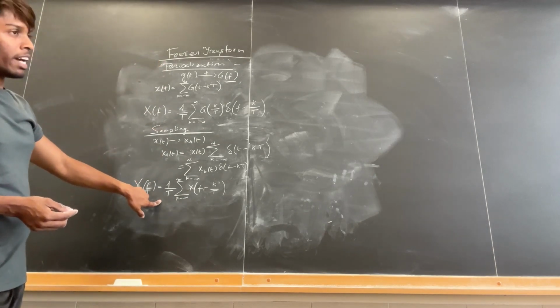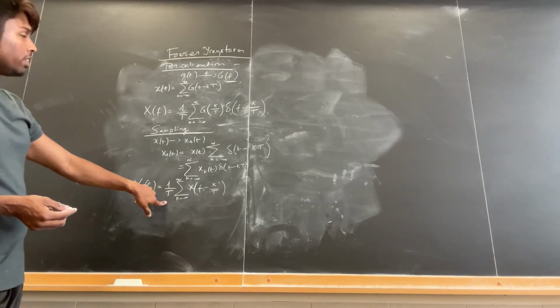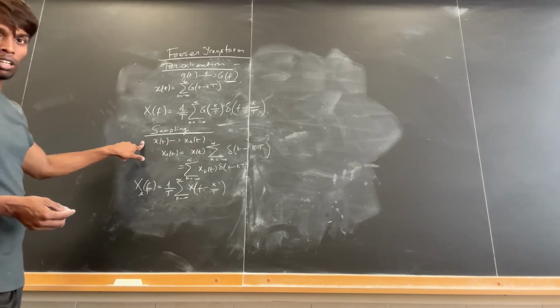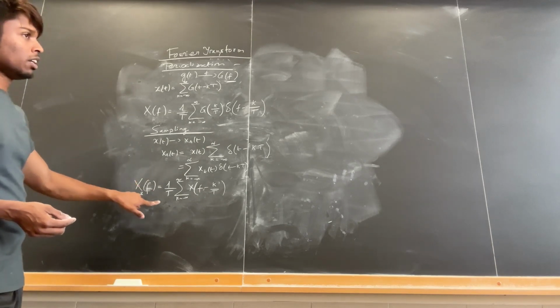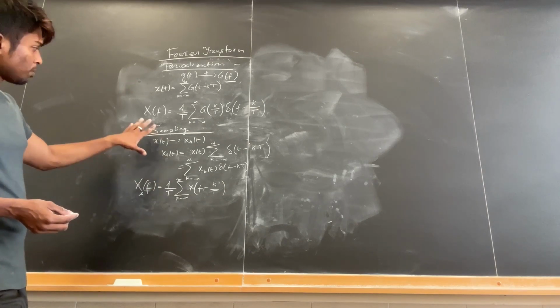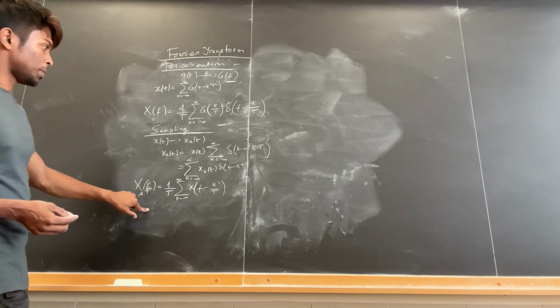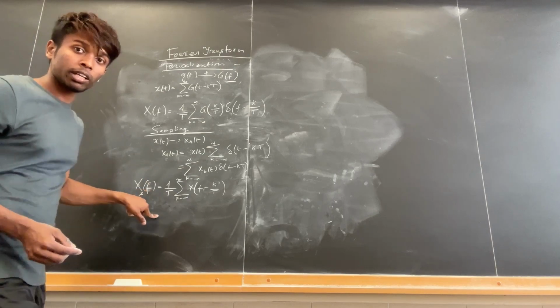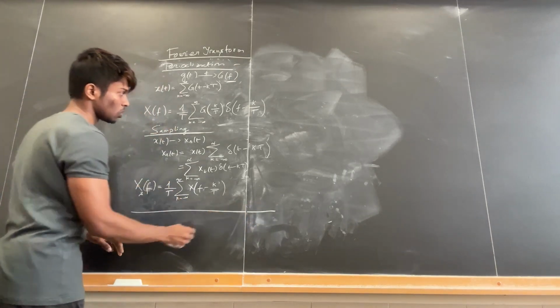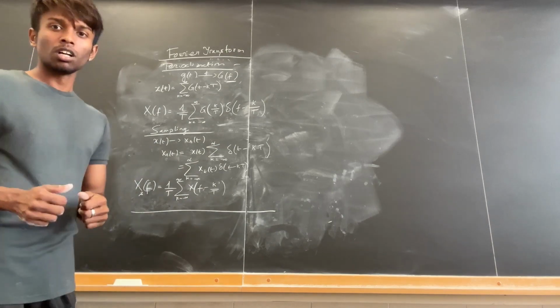So what is happening in the frequency domain is a periodization of the signal. If we sample the signal, the Fourier transform is periodized in the frequency domain. That's the property. So this is the sampling property. And that ends all the properties, all the 10 properties discussed for the Fourier transform.